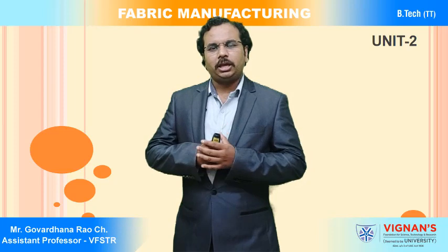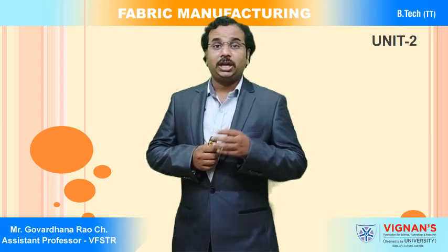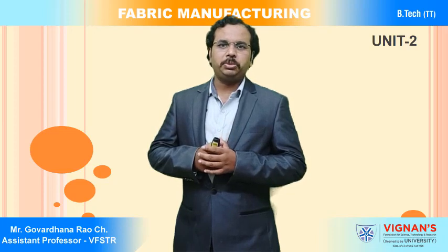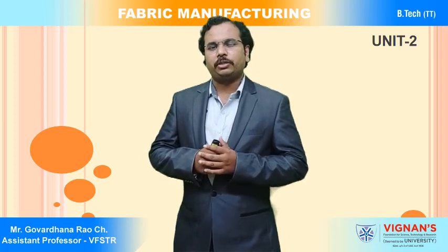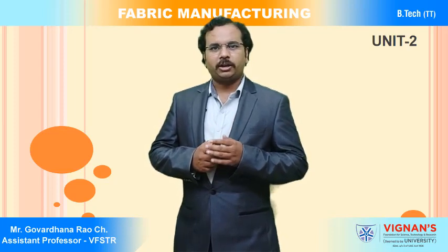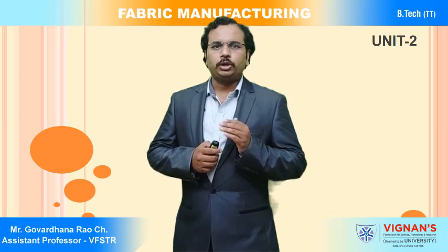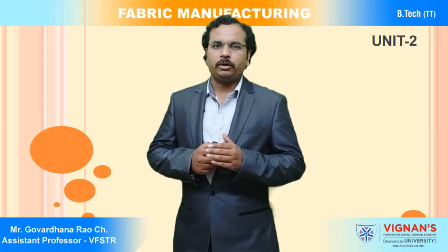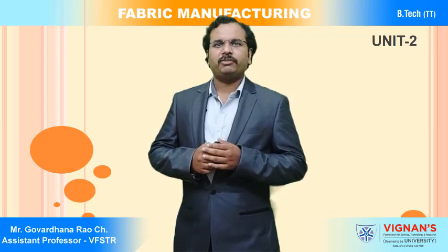Finally, in the sizing process, we have discussed the different faults which are going to be produced, and the causes and remedies for each particular fault, how to overcome that fault in the sizing process, so that we can maintain proper weaving efficiency and proper working conditions in the further process.